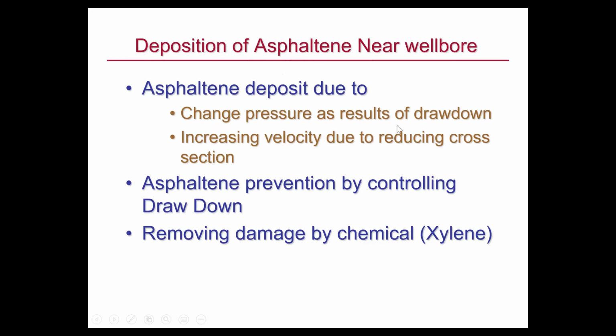And then in the reservoir, the asphaltene or polar components are there. If you have high drawdown, the moving of polar components creates electrostatic attraction, and that can result in asphaltene deposition in the reservoir, which will affect permeability.